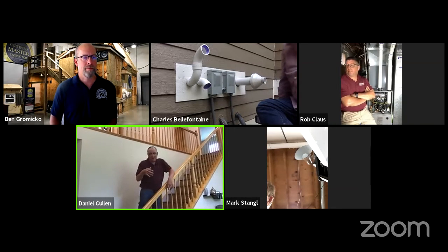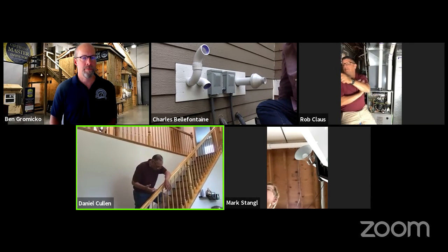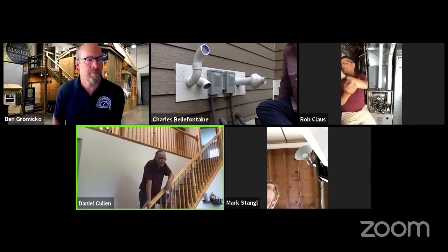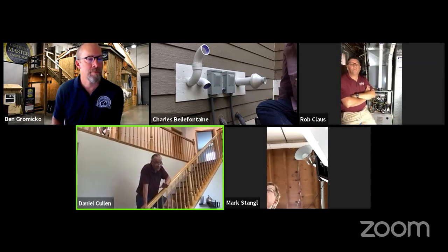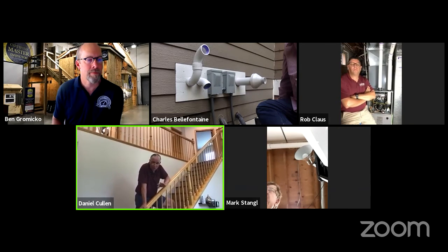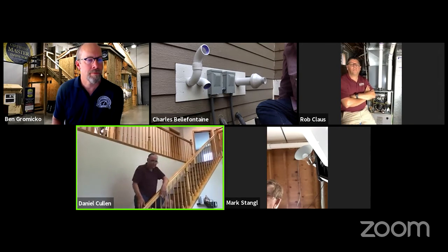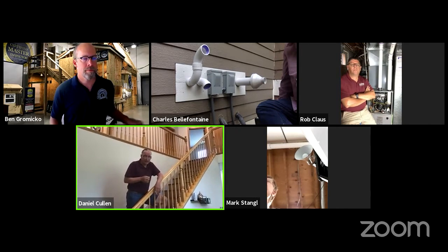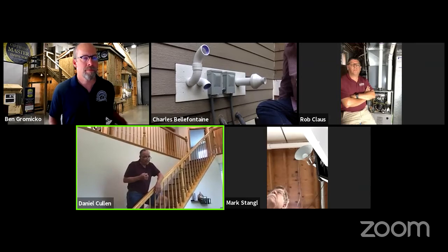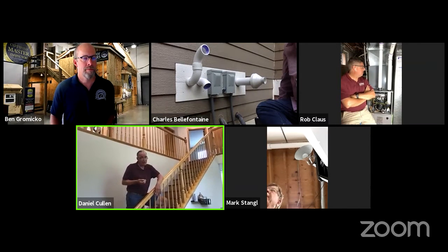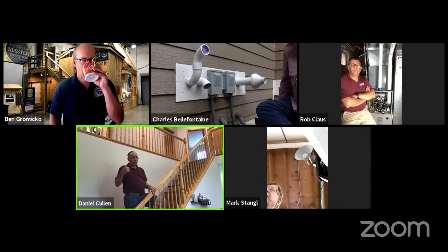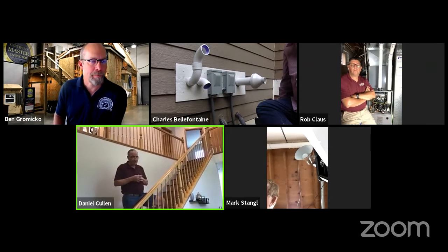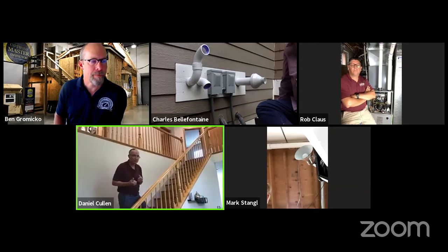In a house like this, if we had a permanent split capacitor motor, the typical motor that you would find on most conventional furnaces, that would cost about $350 a year in electricity to run 24/7, 365. With an ECM motor, electronically commutated motor, that goes down by about a factor of 10. So it'd be only about $35 a year to run your blower motor 24/7, constantly destratifying the air and sending it back out to your supply registers.